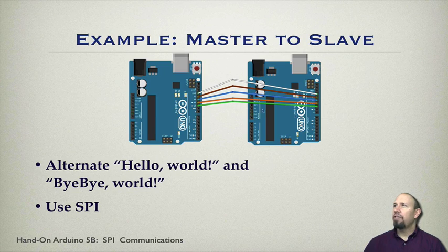Basically we have two Arduinos connected to one another, and again we have the 4 lines connected to each other, and then we have a ground connected to each other. So you need to have that 5th line, a ground, on the communication. Now, what I'm going to be using is the Cat6 cable that I showed in the last lecture, and the Cat6 cable has 4 twisted pairs.